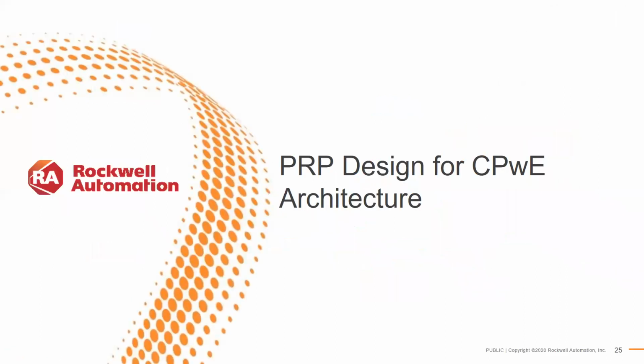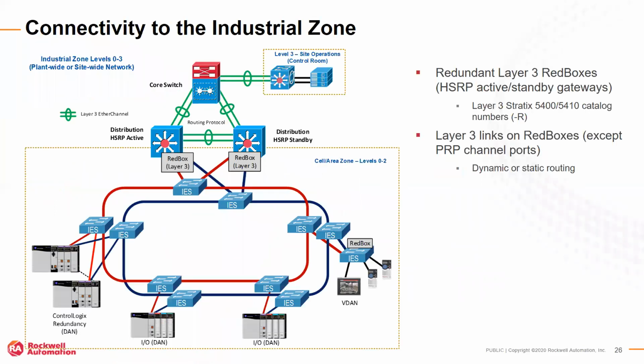So moving on slightly, we're going to introduce PRP as a part of the larger Converged Plantwide Ethernet network architecture. For those of you that aren't aware, CPwE is a methodology and set of design recommendations that have been created with a partnership between Rockwell, Cisco, and Panduit.